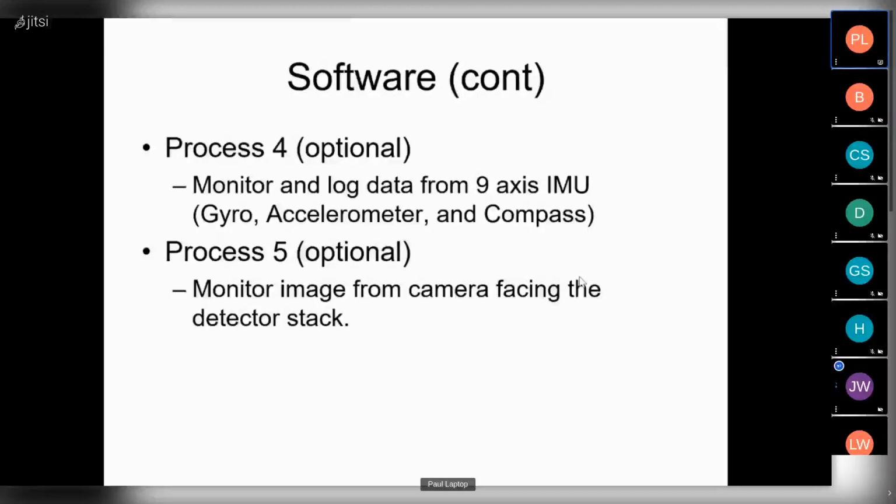Phototransistors have a pretty limited dynamic range. They just tend to saturate when they get some light. They have their own gain. Right. So typically, there's a thing in the industry called light curtains. Have you ever heard of these things? No. So they basically have an array of LEDs or lasers on one side with some optics, so they have kind of a narrow beam pattern, and then they have another array on the other side, in like a 3-foot long bar. There's a company, STI, that makes them, and Banner Engineering makes them.